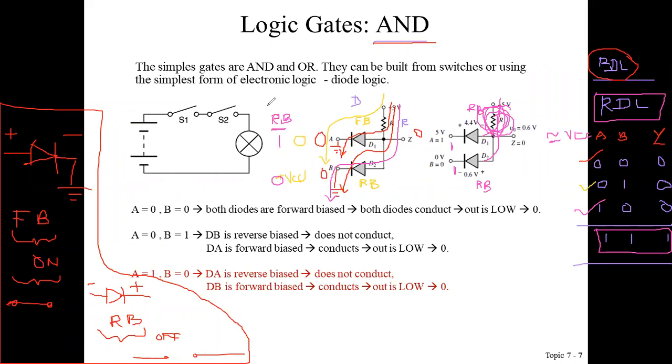What you have to do? You have to write the AND logic truth table, and its simple equivalent circuit, and then this exact circuit by using resistor, diode and plus VCC. So this is RDL family. Then you have to verify all the conditions, inputs and outputs. That's all.